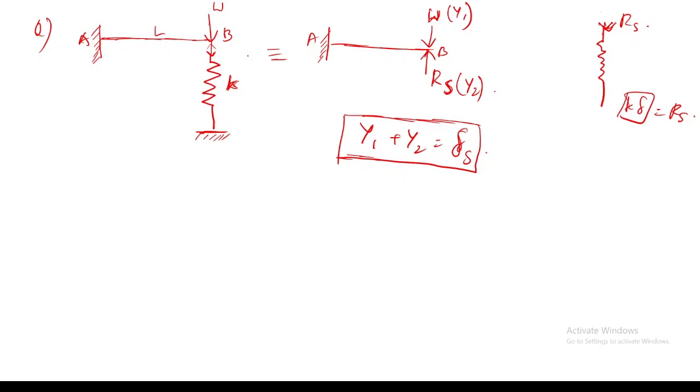For solving these kinds of problems, first you have to draw the free body diagram, and then find the relation between the deflections. Based on this relation, you can write down all the deflection formulae from the formula sheet, and then find the reaction force. So here I need to find the value of RS. Can you find the value of RS here?